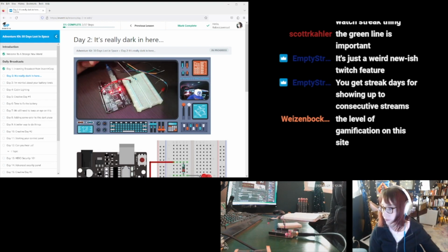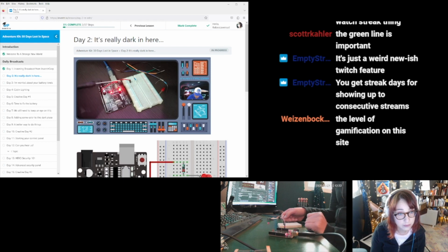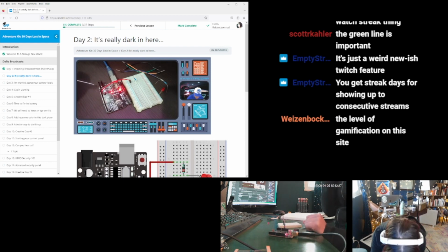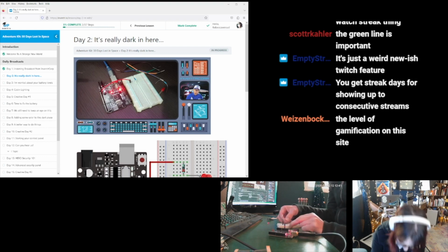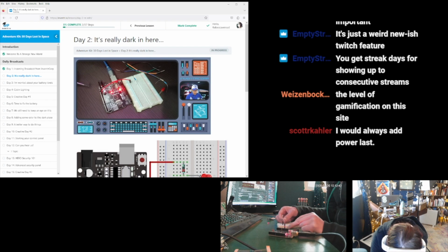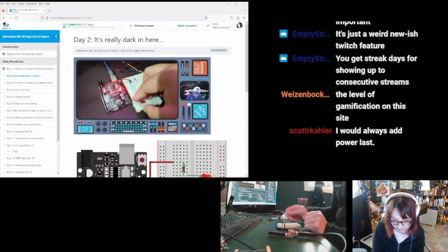If I were to then connect another wire from here back to 0 volts, or ground, where ground is another shorthand name for 0 volts in this circuit, then I would have current flowing through the resistor in a circuit. That wouldn't be too useful because the current really wouldn't be doing anything. So rather than simply sending a wire back to ground here, I'm going to send the current through the LED and see if we can get the LED to light.